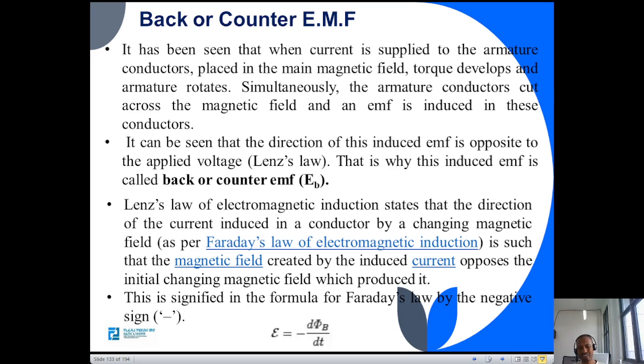Truly speaking, this induced or generated voltage holds true for the generator, because that's the one which is inducing or generating voltage. When we come to the motor, the correct term we usually have to use is the back or counter EMF. Why we named it so: it has been seen that when current is supplied to the